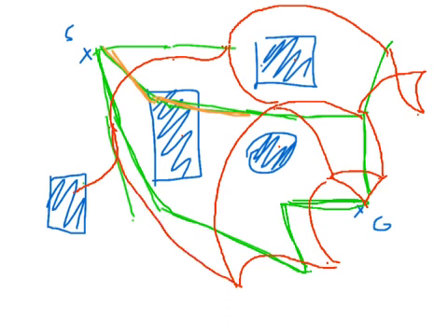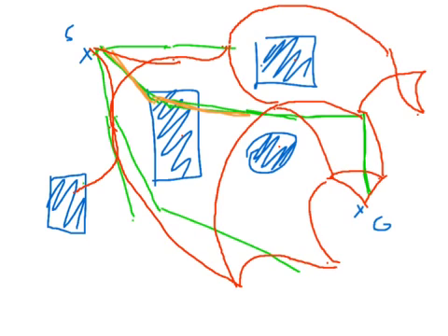Now if I want to find the shortest path between the start and the goal, I can just use standard graph shortest path algorithms such as Dijkstra's or A star to find my path. Let's look at this real quick, and by inspection I clearly see that if I want to go from the start to the goal, something like this path here would probably be my best bet.